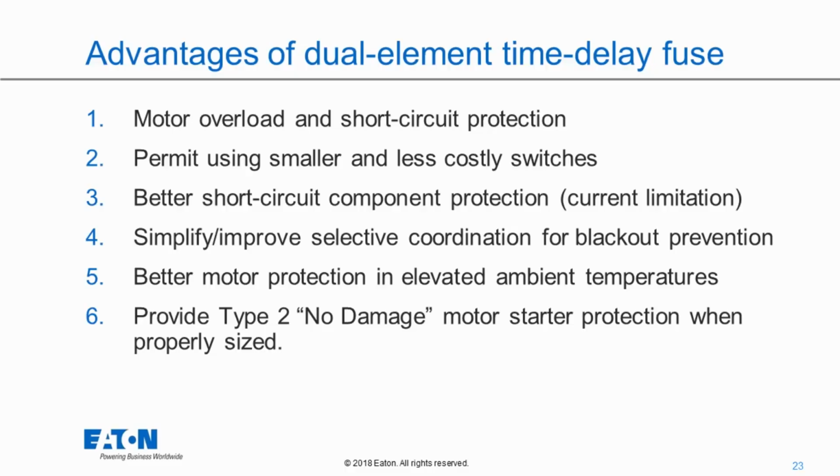And then we have better protection in elevated ambient temperatures. So if you do have a situation that's maybe an elevated ambient temperature, a dual element time delay fuse will certainly work better in those applications. And then finally, we have type 2. It provides type 2 no damage motor starter protection when properly sized.